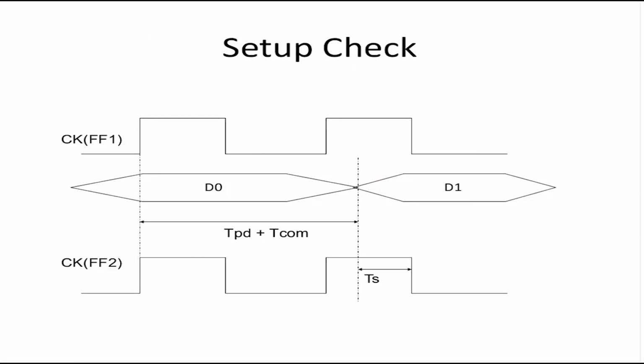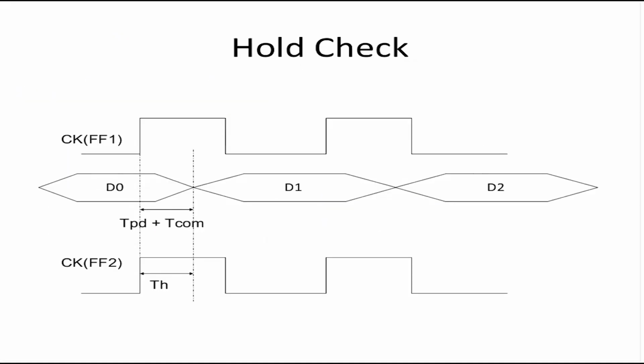And what about the post layout? In post layout, the active clock edge will be either coming late or coming earlier. What if it comes earlier? If it comes earlier, your window is shortened and your setup timing is more constrained. Let's talk about hold. What happens if the capture clock comes later? You are more constrained for hold. It's a problem for hold if the capture clock comes later.